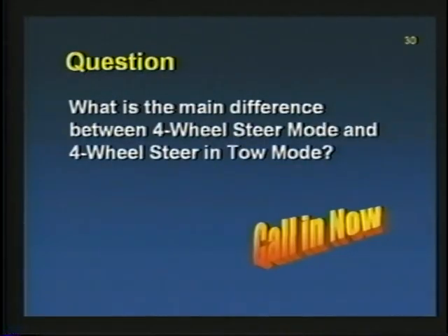We're still using negative, neutral, and positive phase. We're still going to turn the wheel 12 degrees in negative phase and 5 degrees in the positive phase. So we're not turning wheels any more or any less. Now that you know that, what do you think is occurring differently? Go ahead, please call.